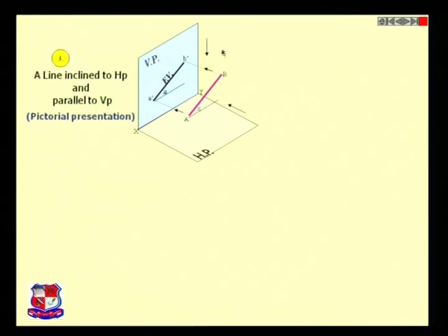Now if we talk about the top view, as you can see over here, we are looking from the top. You might know that the top view projections will be traced on the horizontal plane itself. So if we are seeing from the top, it would be landing on the horizontal plane like this. These two lines are tracing a line on the horizontal plane, but if you are tracing any sort of inclined line into a straight line, then its length would be reduced. That we will discuss in the later part. This would be the top view, always denoted with the small letters a or b.